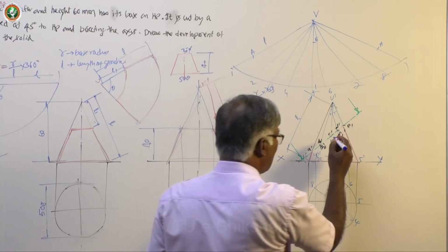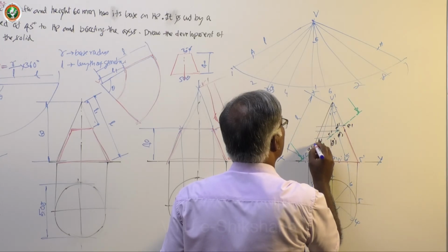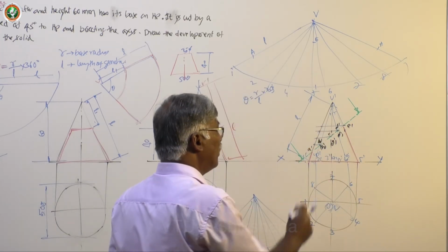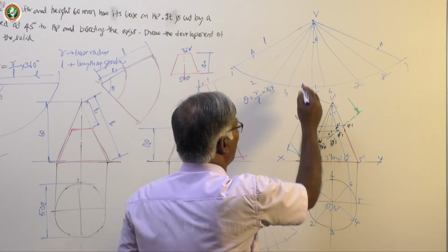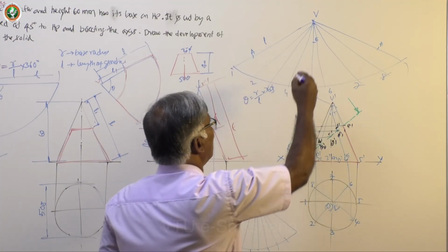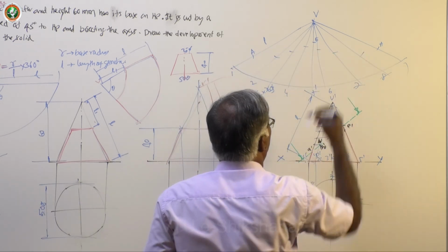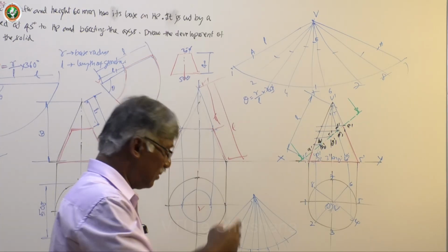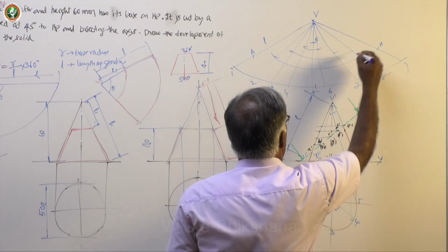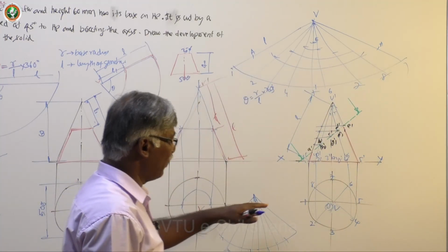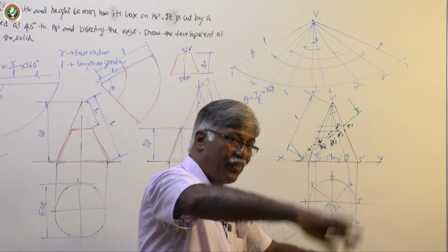You project all these points onto the true length line, including E you can make it because you will get a sequence. In sequence you get. What you do is you take the first line, draw an arc, second line, draw one more arc covering 2 and 8. Like that you do. So in that case you will get this way. Or simply draw arcs only. First arc, second arc, third arc to cover the corresponding generators. See for example here after 1 you have to cover V2 and V8. Till that point you draw arc.